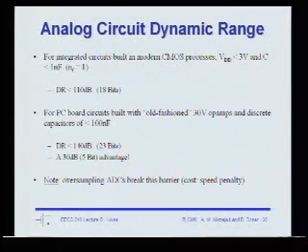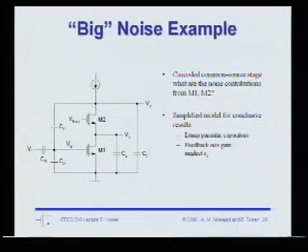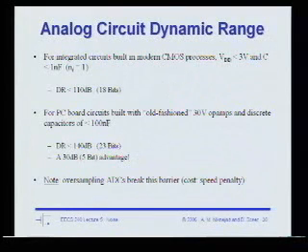So definitely going on chip is not all better, right? Everything does not improve. You actually pay a big price for going to a lower supply voltage. And as many of you know, this is in contrast to digital circuits, where lower supply voltages and smaller capacitors are actually a good thing, right? Smaller capacitors mean less CV squared power. Lower voltages means less V squared in that CV squared. So definitely scaling in some ways is bad for high dynamic range analog circuits. All right, questions or comments? Philosophical comments? Anybody want to contest that?